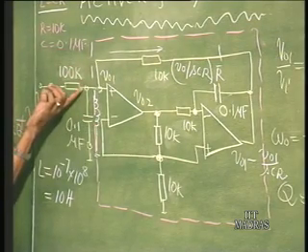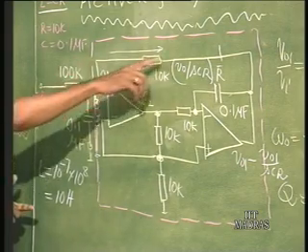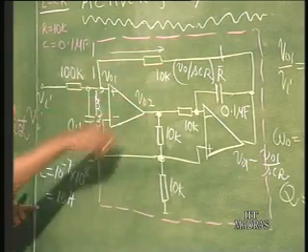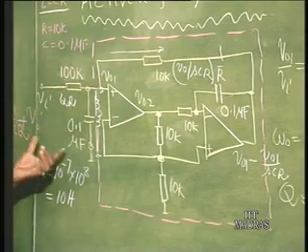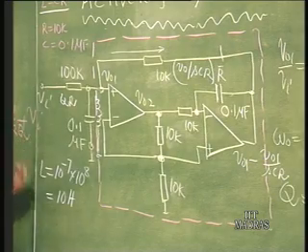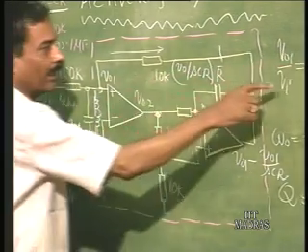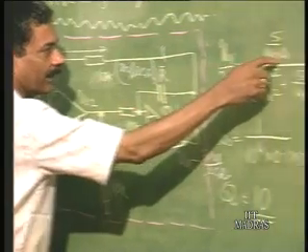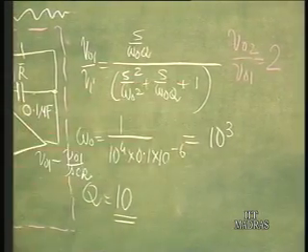And then if I connect a resistance R times Q, R is the 10 K resistance that has been used here, here it is Q times R if I use. This is really a tank circuit with L, C and R, okay, and therefore, its transfer function from V naught 1 by V I is going to be S by omega naught Q divided by S squared by omega naught squared plus S by omega naught Q plus 1.